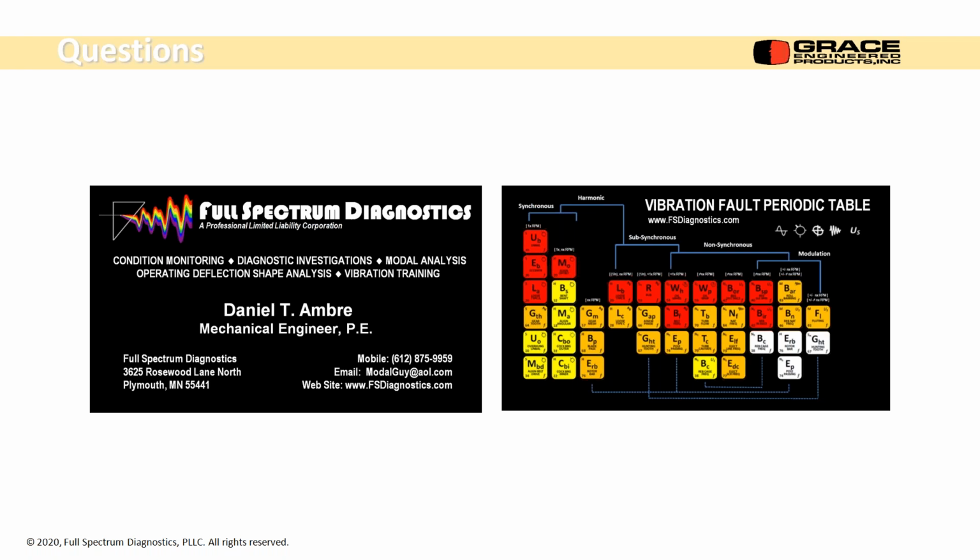If you can average it, I didn't think about that. I guess you can average it over time, but if you're randomly throwing scrap in there, it's just going to affect the noise floor. So as long as your peaks are above that, you'll still be able to pick out the peaks. I'm not sure if you can tell real well if it's good or bad as far as the condition of the fan that's pushing the stuff through.